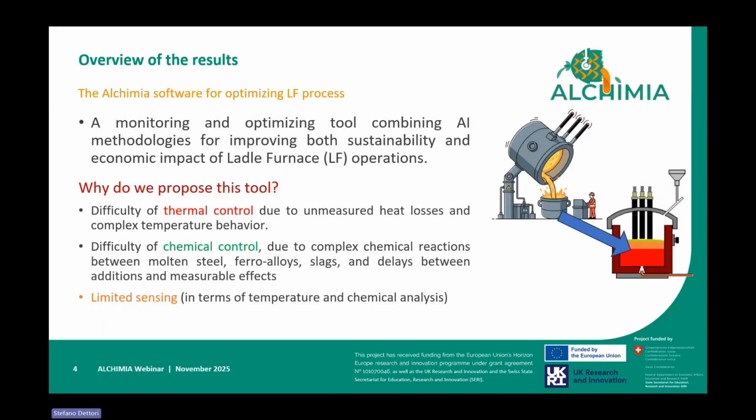the chemical reactions and the interaction between the molten steel, the additional ferroalloys, and also the oxidizers and the slags that are above the steel. Also, there are delays between the additions the operators make and the measurable effects, because there is a limitation in the sensing. First in terms of temperature, because temperature is sampled every more or less 5 to 10 minutes.